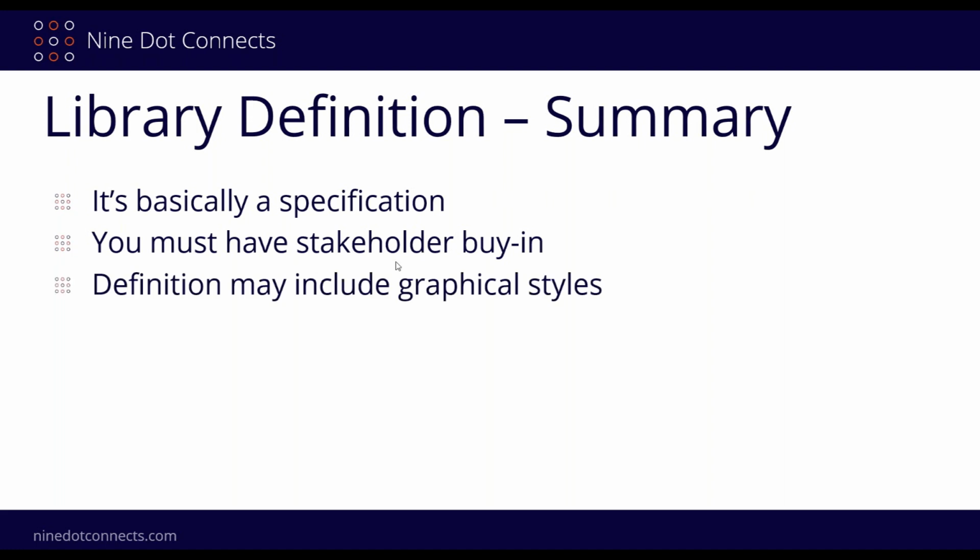Definition may include graphical styles. Now, if you remember at the beginning, I talked about three things: the database, the component, and the graphical styles. And I find that ultimately you are going to have to deal with graphical styles, which are the symbols and the footprints.